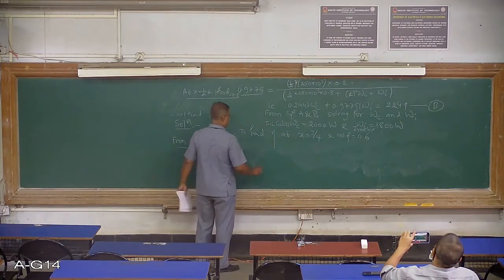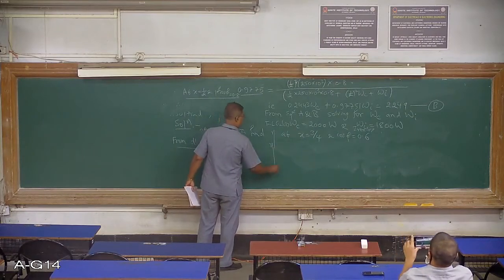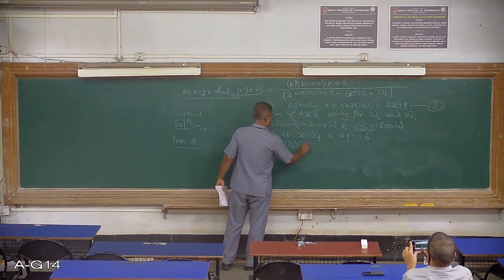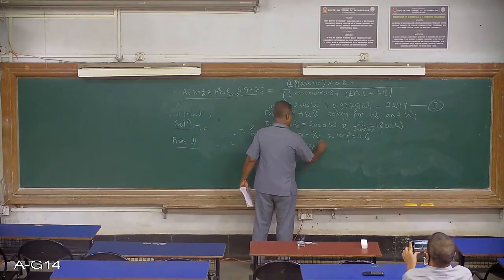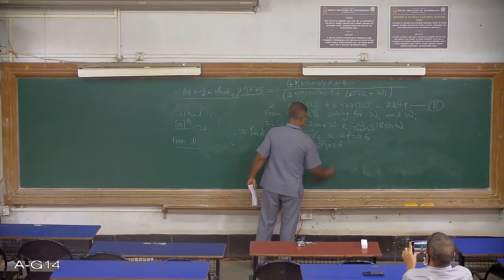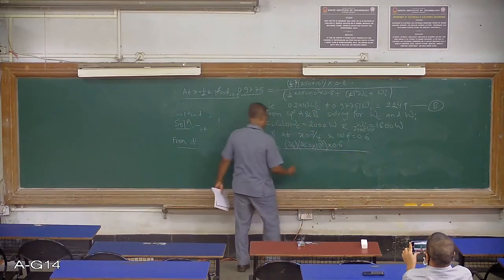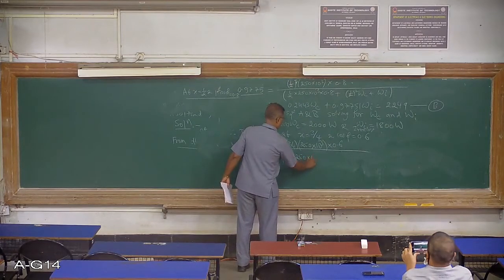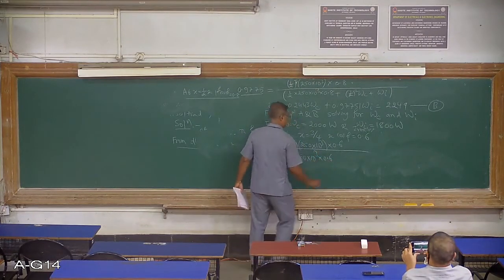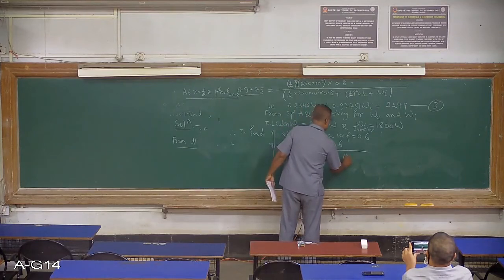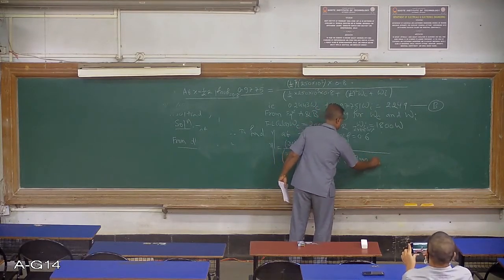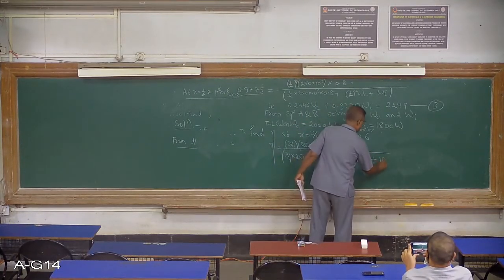Once again, using the same formula, you will be calculating the efficiency equal to 3/4 into 250 into 10 raised to 3 into 0.6, divided by 3/4 into 250 into 10 raised to 3 into 0.6 plus 3/4 squared into WC 2000 and WI 1800.